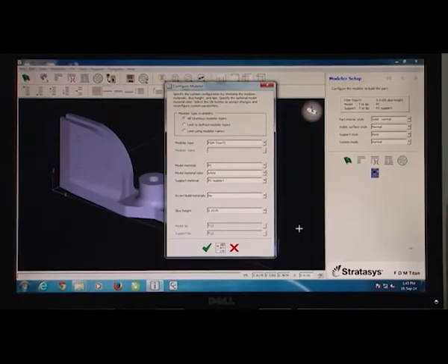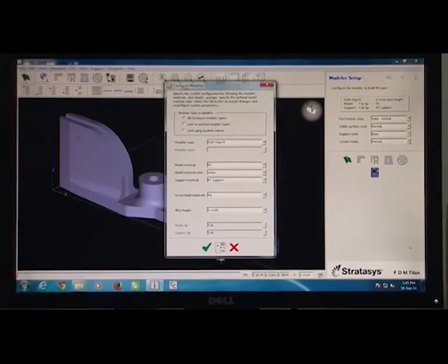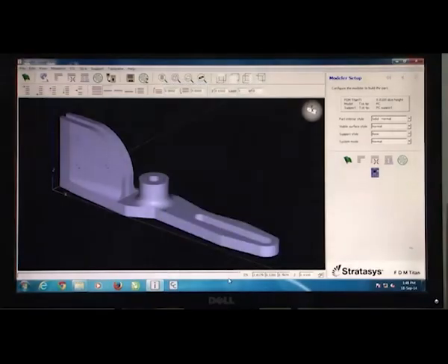So it is very obvious that the software is quite friendly. It will minimally work in a manner so that it tailors all these systems. Finally we make it okay by pressing on this right button here. So now you can see the text box which comes here on the top is mentioning FDM Titan T1, slice height of 0.01, model of T16 tip to be used, a polycarbonate part and a polycarbonate support.